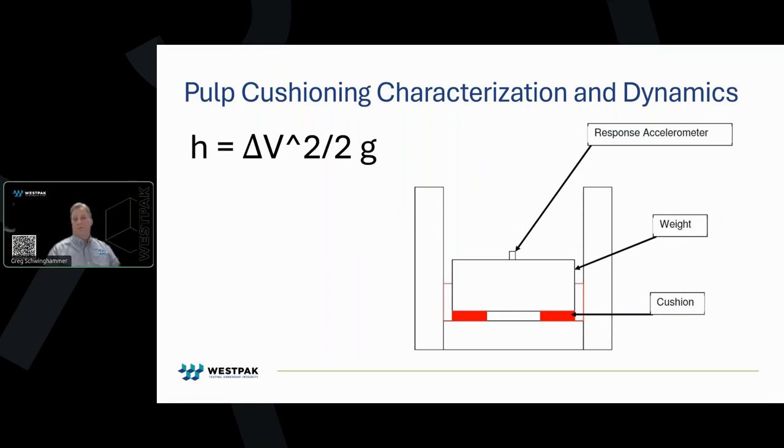So looking at molded pulp as a solid material, pulp cushions generally have poor dynamic properties because of their relatively high stiffness and lack of compressibility. Pulp becomes a legitimate cushioning material primarily as a function of its shape and deformation or crushing of that shape, assuming that the material can be characterized as a rectangular prism and functions in a compressive manner. So if you have a large block of molded fiber, that's not going to work as a cushion. You need shapes and something to deflect to be able to give that cushioning property, like a polyethylene or EPS foam.